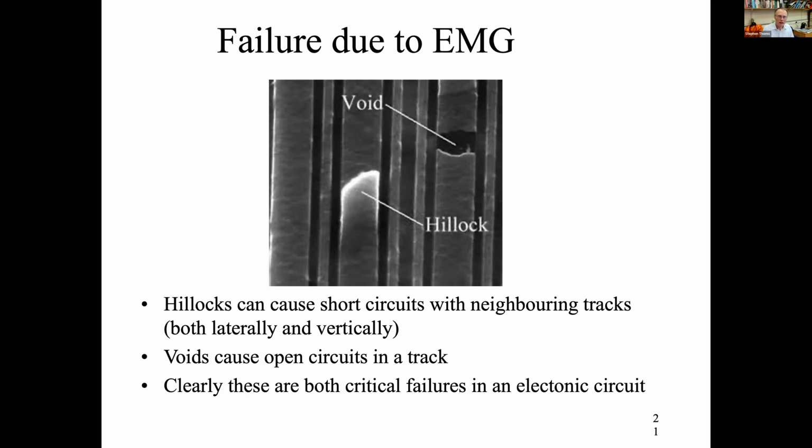The other thing to note is that electromigration is much more severe in aluminium, and it's reduced if you add a little bit of silicon to the aluminium, which is what people did originally. They said, well, we add some silicon, it strengthens the aluminium in the sense that there's less electromigration, so that's good.